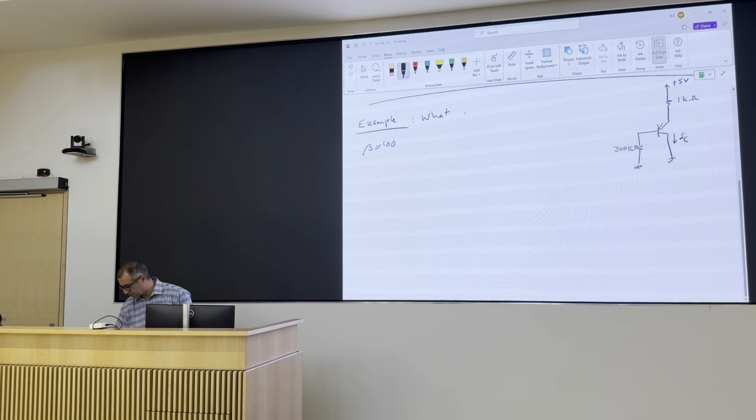So if you had like 5 milliamps of current going down, now you're pushing 2 milliamps going up. So it's 3 milliamps now instead of whatever it was before. And so that's the first thing you notice, that IC is dropping. The other thing you notice, if you're careful and if you have instruments attached to a transistor, is that the ratio of IC to IB is changing. The ratio of IC to IB, if the device was in active region, was your beta. It was a large number.